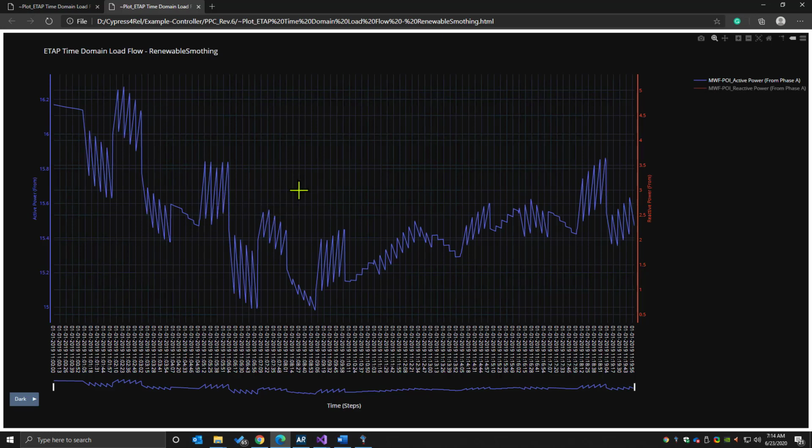Of course, you can go through a couple of iterations and find the appropriate energy storage size and the appropriate tightening of the controller to ensure that you smoothen out these fluctuations and achieve a tighter band in terms of real power adjustment.